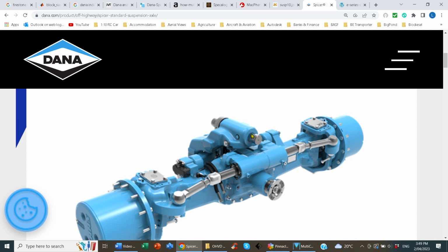This arrangement requires the axle to move laterally as the suspension works. And on many aircraft towing tractors, I've run a beam from the mounting pad on one side to the mounting pad on the other and put the pivot pin in that beam, effectively creating this arrangement, but with an axle that wasn't available with a complete equalizing beam pivot already in it. Ideal for big, heavy loads moving at slow speeds.